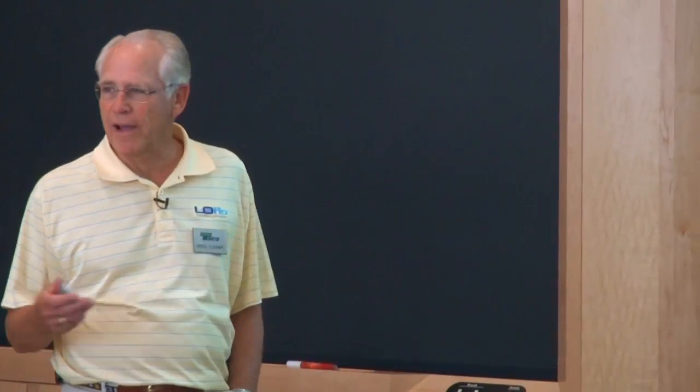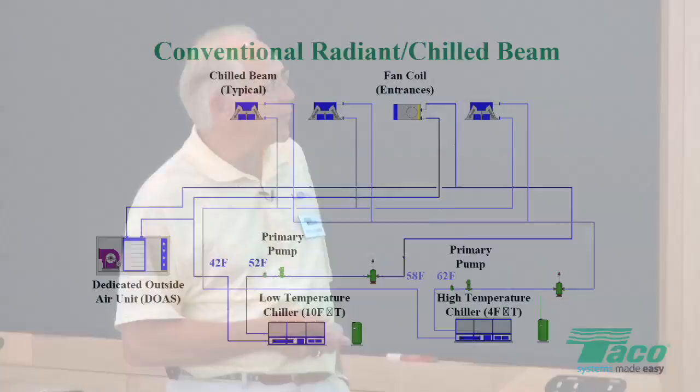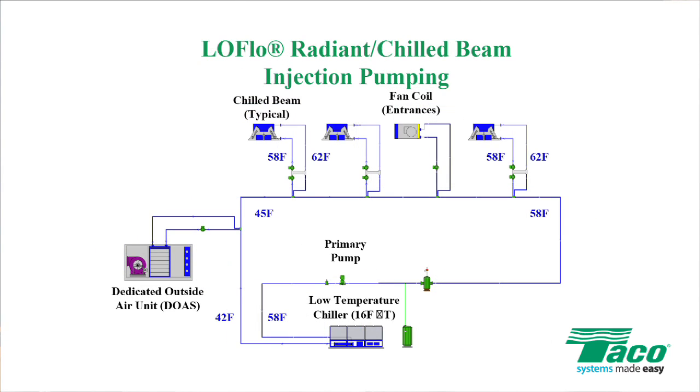What we are noticing is that a lot of these jobs are going over the money because you get double the number of components in here, double the number of pipes. So let's go back to our old friend, the single pipe system, and we can make that look like that. This does a couple of things for you. We can get a very high split now.